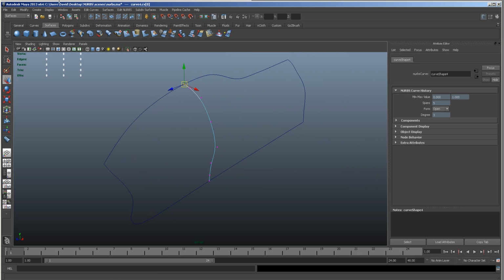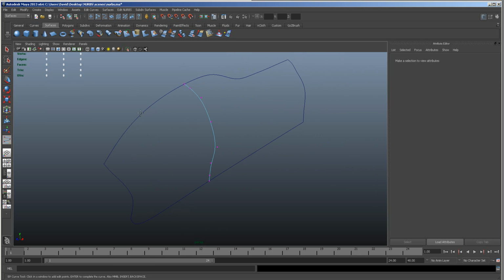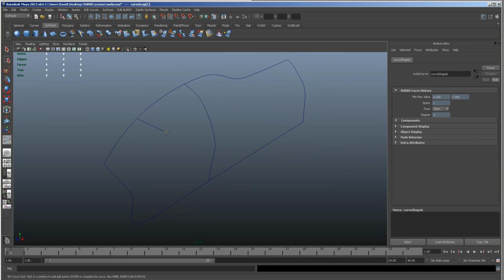So that's why I tend to build the rails, and when I'm creating the EP curves, I press the C key and then it will allow me to snap directly to any curve. So I can do around like this, then I can C key it onto here, or down to here. Press enter and I know that it's formed nicely. Of course you would go in there and move this as well to wherever you wanted it. Something like that, or not.